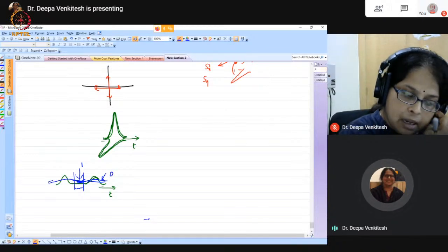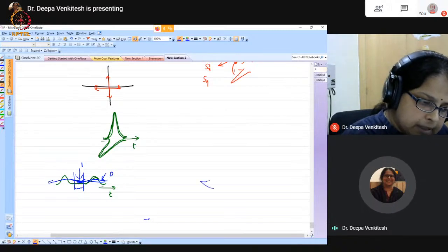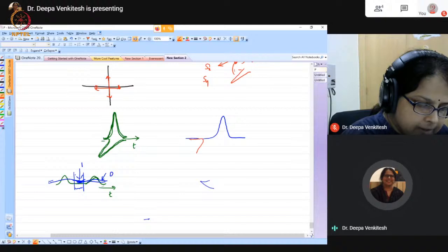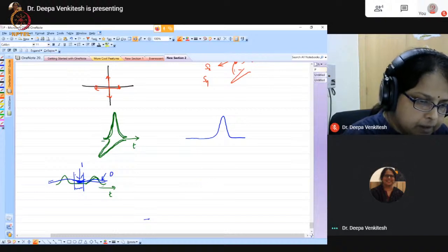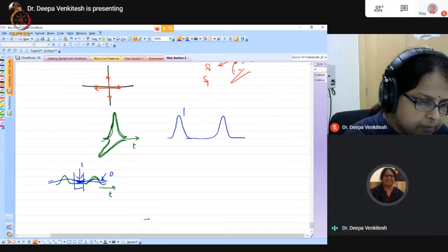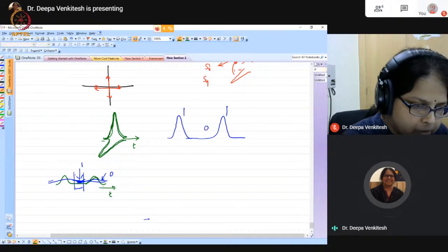Now, how do I understand PMD? If you have a delay, it means that one of the components is traveling faster and the other component is traveling, let's say, slower. So you had a 1, 0 and a 1 in the X polarization, of the same heights. Let's say 1, 0, 1 traveling along the X polarization. It's a very crude picture I'm drawing.